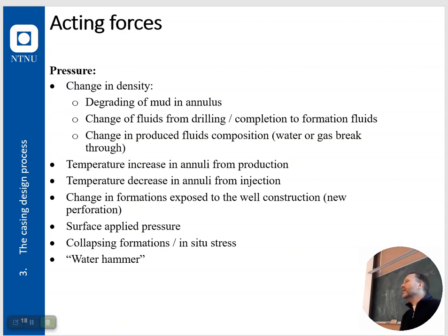Shocks. If you say that you have a glass plug in your well and you release it with pressure, have you heard about glass plugs and these type of things? It's a plug that you pressure up to a certain pressure, and then you bleed off that pressure, and you do these cycles a number of times, and then there's like a detonation, and it explodes, and it turns into very fine sand.